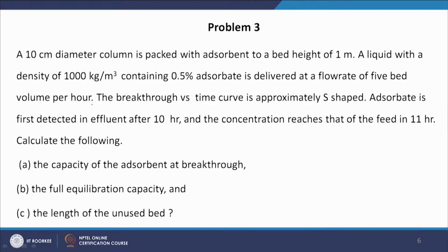The breakthrough versus time curve is approximately S shaped. Adsorbate is first detected in the effluent after 10 hours and the concentration reaches that of the feed in 11 hours. Calculate the following: the capacity of the adsorbent at breakthrough, the full equilibrium capacity and the length of the unused bed. So, this is again a problem of adsorption in a packed bed column.